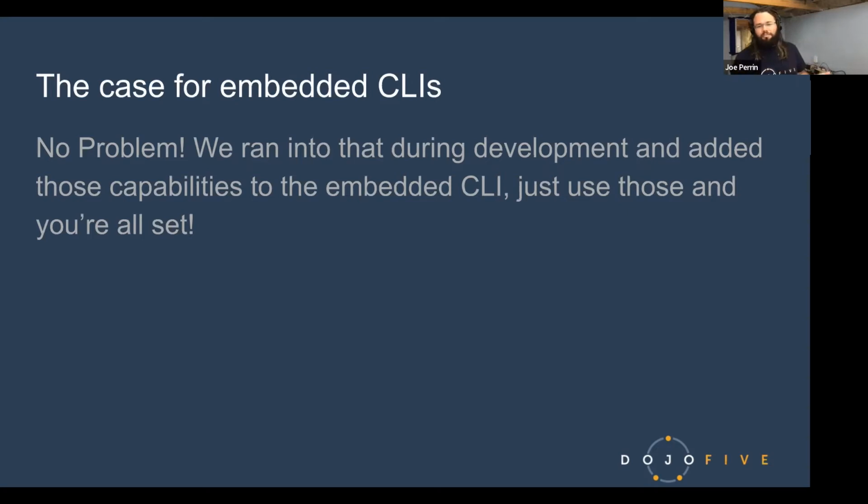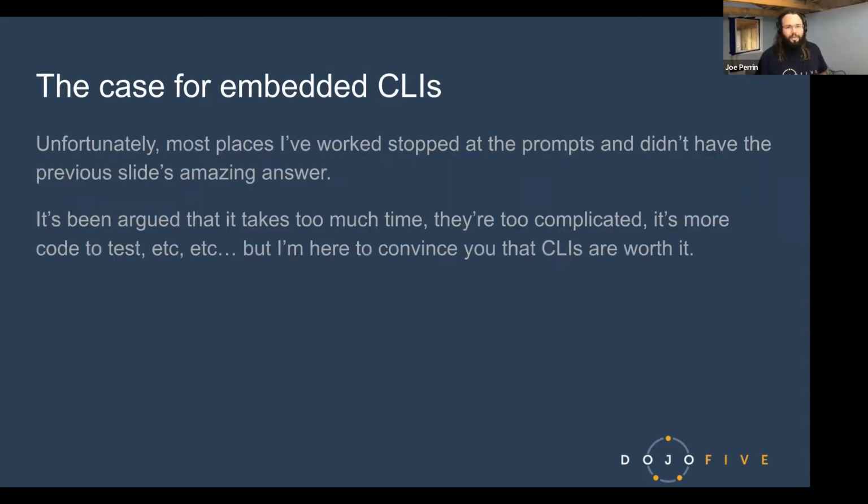And we'll talk about how it doesn't have to be UART, doesn't have to be RS-232, RS-485, any of those. We'll talk about other interfaces we can use. But the main thing is that you have an interface that's easy to use. You can type some commands and execute those hooks into your code to elicit specific behavior.